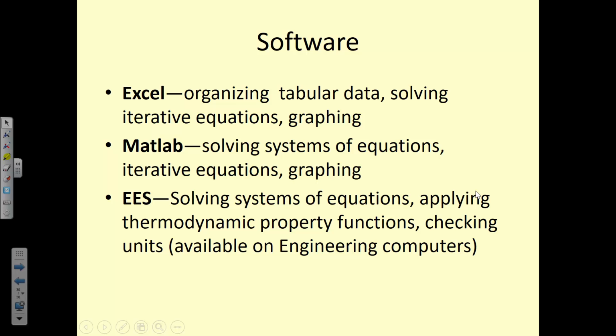And then EES, of course, is very awesome. If you solve problems with EES, they will be slightly different than looking them up in the book because the property tables are just a little bit different in EES, but it's kind of nice. We'll do some examples this semester where we learn how to use it because you can use it to directly look up property values for you as it's solving the equations. So you don't have to go to the book and look stuff up. You just give it two independent intensive properties at the beginning as you define your system, and then it'll find all the other property values for you, which is really cool.